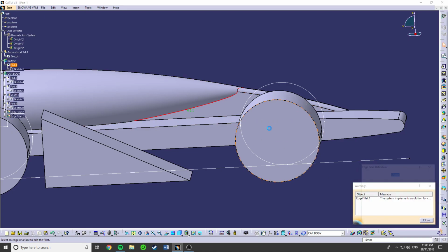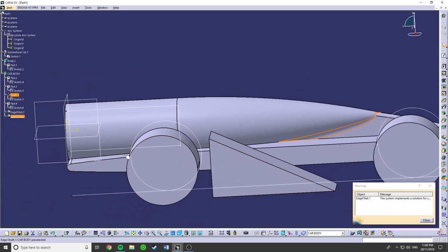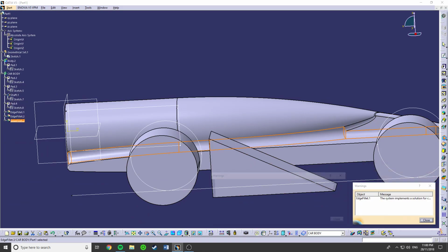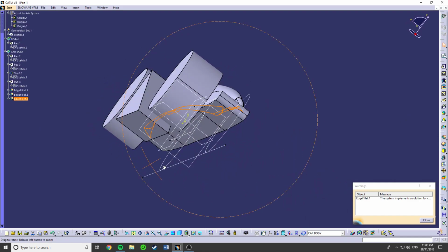But you have to use a 6mm drill bit, so you have to use a 3mm inside fillet to keep the shape consistent. Then we can use 3mm there, and that gives a nice-ish shape. Obviously it's a bit ugly, but it won't really matter.